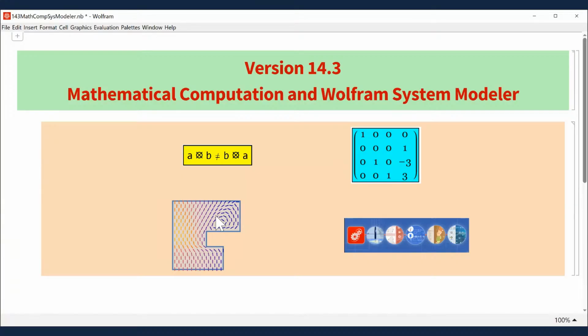So this beautiful talk on fluid dynamics is our third talk for today, the first applied talk, in contrast to the first two. And some people talk about distributed modeling, by which they mean that when you do the finite element method, you have a large geometry and you have partial differential equations, etc. But then at the other extreme, you have so-called lumped modeling, which is what System Modeler does, where you have small components, and those components are now governed not by partial differential equations, but by ordinary differential equations.